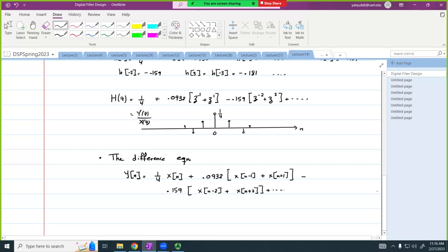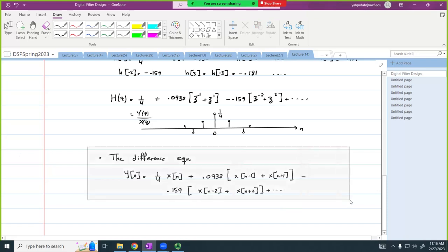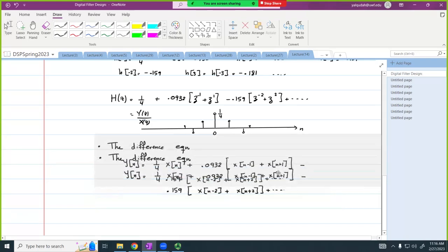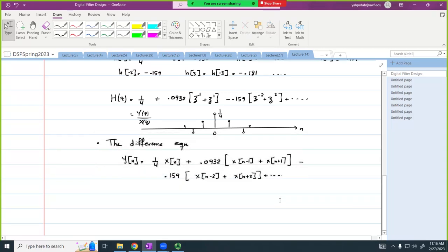If you look at this filter, what do we notice about this filter? Non-causal. It's non-causal. Excellent. It also would be a finite impulse response. Excellent, because it's not based on any of the outputs. Excellent. So if you look at this filter,